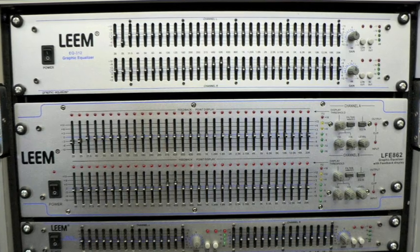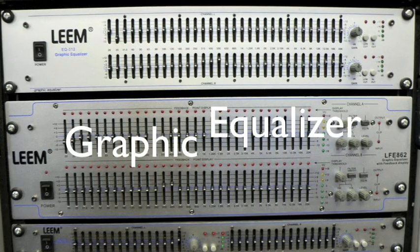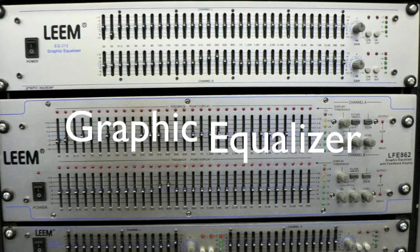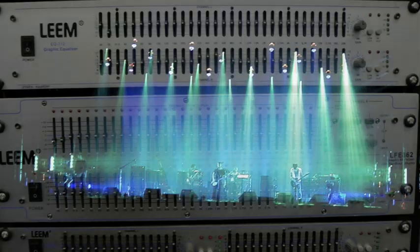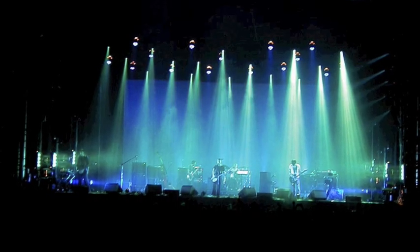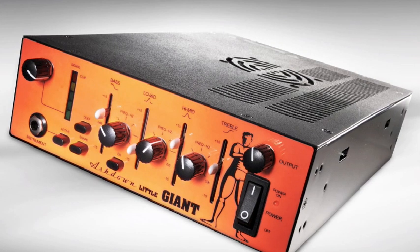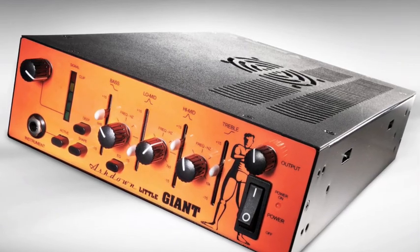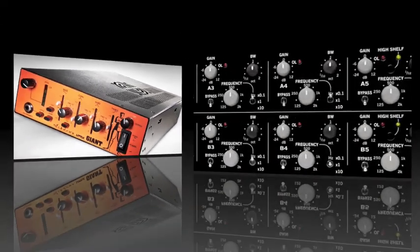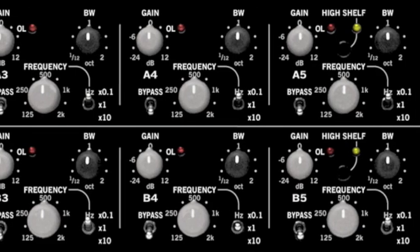There are three kinds of equalizers based on the range of feature controls. Peaking or graphic equalizers provide a set of given fixed bandwidths at which the user can raise or lower the gain. Such equalizers are often used in live sound systems and semi-professional equipment due to their limited parameters. Semi-parametric equalizers also have the ability to control the center frequency at which the gain setting is applied. Parametric equalizers can control gain, center frequency, and bandwidth.